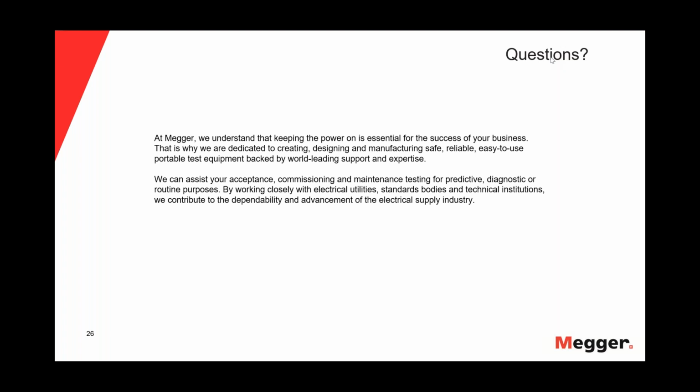Thank you, Javier. Additionally, is a DC high-pot test a prerequisite for a VLF test? No. Indeed, for XLPE and EPR cables, the DC high-pot is no longer recommended. We only recommend using the DC high-pot on paper insulated cables, okay? But no, for sure, if you are dealing with solid dielectric cables, EPR or XLPE, the only thing that you need is the VLF, and indeed the DC high-pot is no longer recommended.